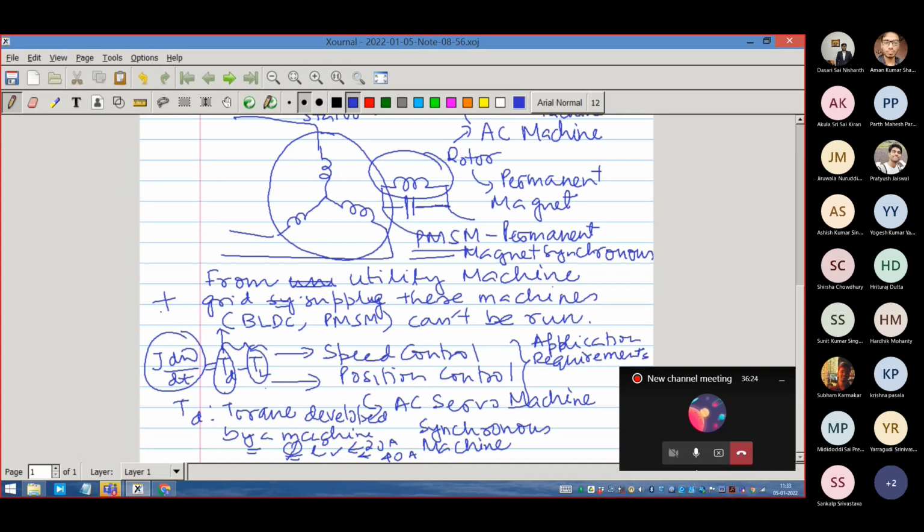I only asked you to go up to 500 rpm, but you have gone beyond. Stop it. So if the speed has gone up, a torque will be developed that is less than that. It can produce a zero torque or a negative torque. When it produces negative torque, Td minus TL is negative, then it will decelerate.